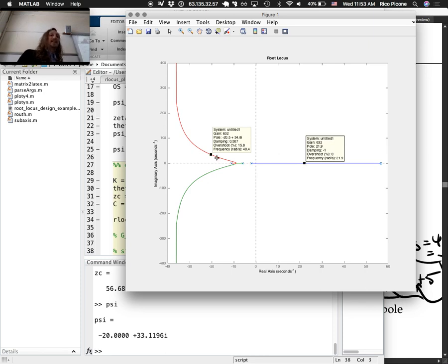So we did succeed at making our root locus go through the point we desired, but we ended up with an unstable system, which is a total bummer. But that is what can happen when you can't specify all three poles. You can't do real pole placement. You only place one at a time. You only get to choose one, you couldn't choose all three.